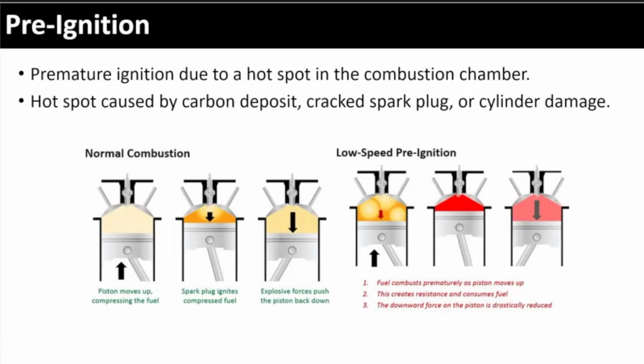Pre-ignition. Pre-ignition is the other bad thing, right? We've got detonation, we've got pre-ignition. In a normal cycle, the cylinder is coming up, the compression happens, you get that power stroke, nice and smooth, and it goes down. In pre-ignition, the ignition with the spark plugs happens early. So when that piston is on the upstroke, it's prematurely getting the power to push it back down.